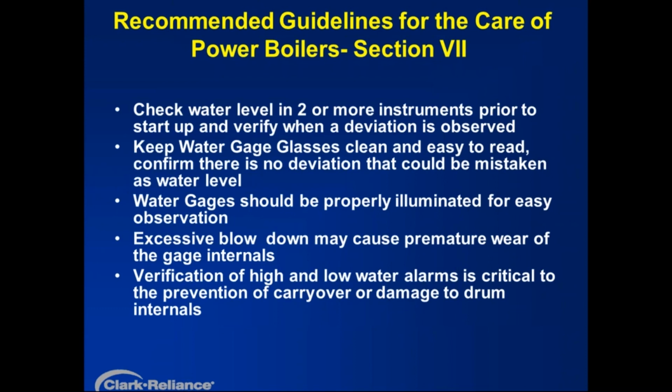Cautioning that blowing down these devices, opening the drain valve excessively, meaning too long a duration, we recommend 20 seconds as a maximum duration. If 20 seconds doesn't clean a level instrument, minutes is not going to do any better. In fact, it will do more harm by wearing and tearing away at valve stem packings from within the center of the valve rather than trying to help yourself. And checking your high and low alarms is critical. That's obviously going to prevent boiler damage and carryover in the steam output.